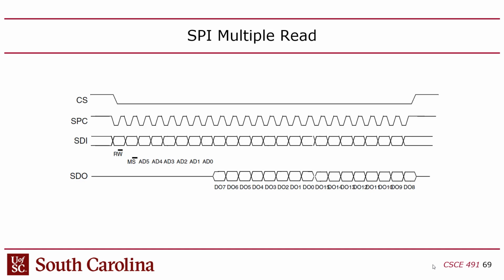You use another bit to indicate that the address I give you is just the first in a series of reads or writes, right? So this way, you could stream audio or something over SPI. You can basically say, here's the first address, and just give me everything starting at that address. And so in that case, the number of cycles is going to be 8 cycles for the header, and then 8 times the number of transactions for the payload, right? So in this case, this is 8 times 3. This should be 27 cycles. Doesn't look like 27, but it is.